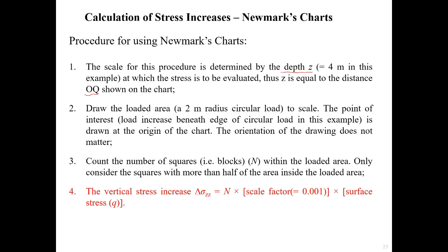And then we plot the loaded area to the scale, because the OQ is already confirmed. So we are able to plot the loaded area. We need to put the point of interest, which is the load increase beneath the edge of the circular load, for this example, at the origin of the chart. Also be aware that the orientation of the drawing does not matter.